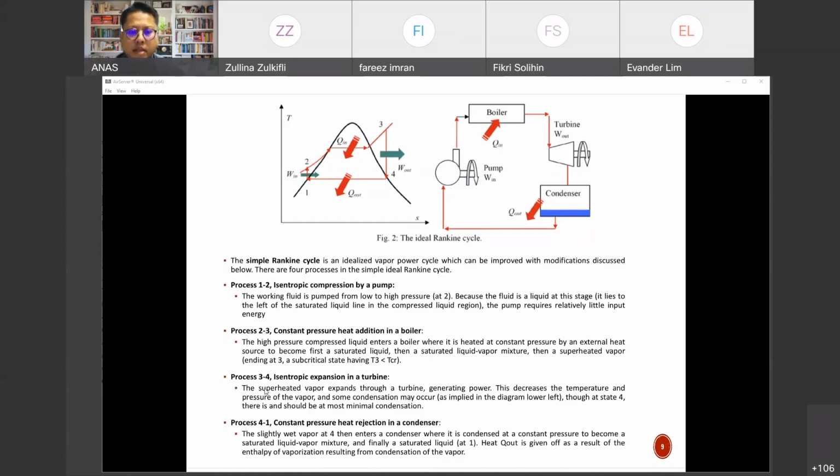Okay, I think the takeaway from this diagram is that you first need to understand how this ideal Rankine cycle differs from the Carnot cycle for the vapor cycles. That's one thing, especially for example here. I emphasized just now that for the Carnot cycle we have a two-phase compression system, which doesn't make any sense. But right now we are just focusing on compressing the liquid,